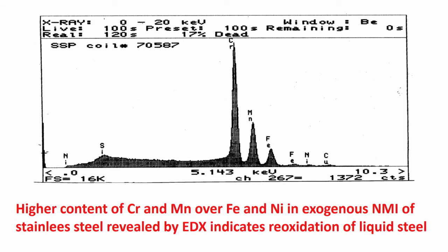So, what is important to identify is that from normal steel you find only peaks of those elements which are present in steel, like iron, chromium, nickel, manganese. You do not find any attachment, any entrapment here, because had there been anything else you would have found a lot of other elements. Now, for the same stainless steel, we will go to another area where there is a defect. How does it look in a scanning electron microscope, and what will the EDX peak tell us?